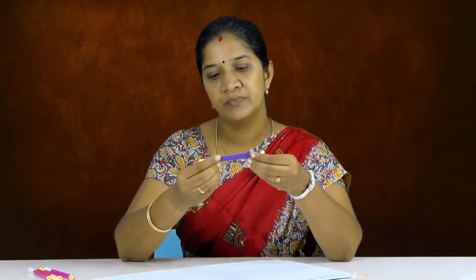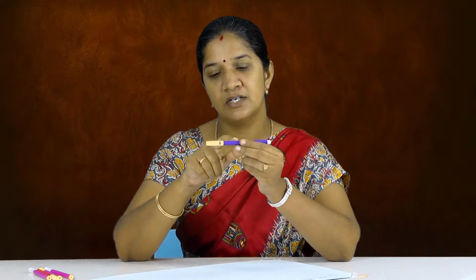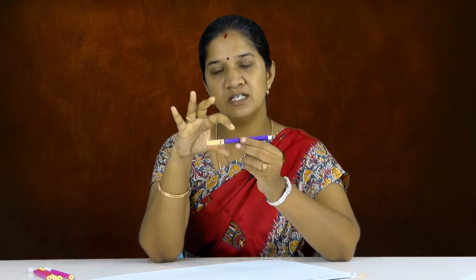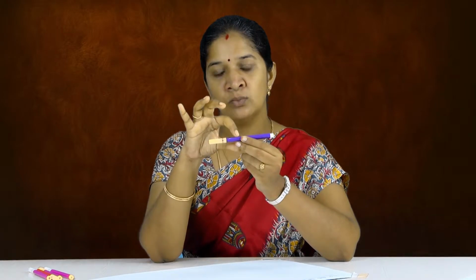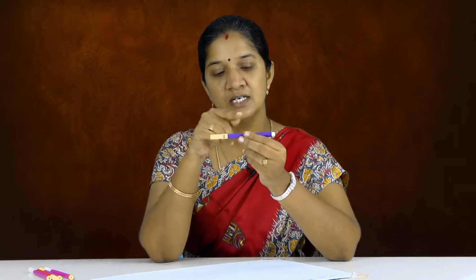Now we will define what is meant by shear, what is meant by shear stress, and what is meant by bending. For example, this is a beam having its axis in the horizontal direction. When it is carrying its load in the transverse direction, it will be subjected to bending. This behavior is nothing but flexure. When a member is carrying a transverse load with its own axis in the horizontal direction, you may call it a flexural member, right? The member has a bending moment in a varying fashion, that is at each and every section the bending moment will vary.